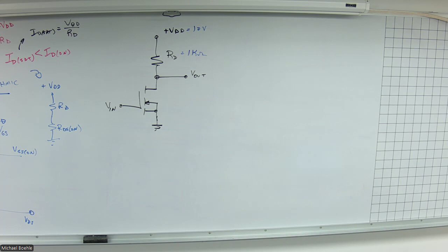So a small signal enhancement mode MOSFET, for example, my VN10LM. Actually, we'll change things a little bit here. So the VN10LM has a gate source threshold voltage of 2.5 volts, a gate source on voltage of 5 volts, and an RDS on of 7.5 ohms.